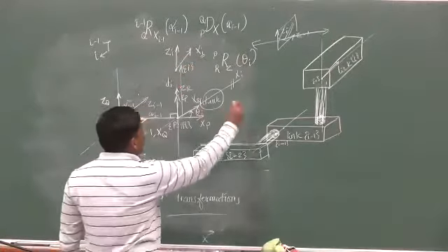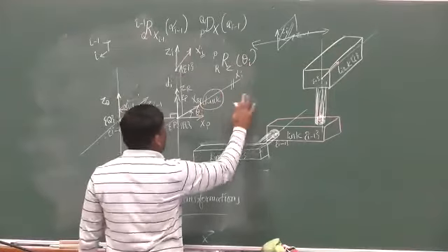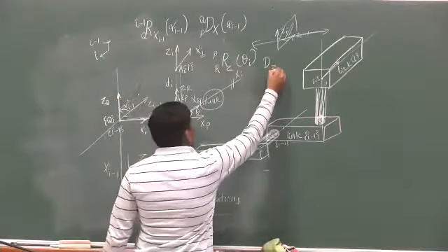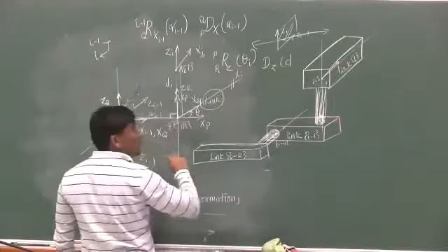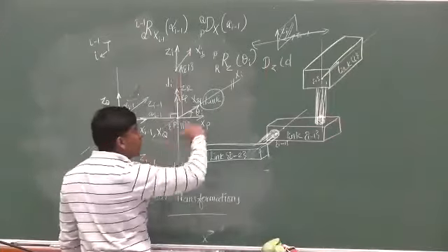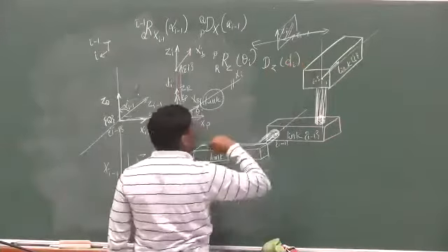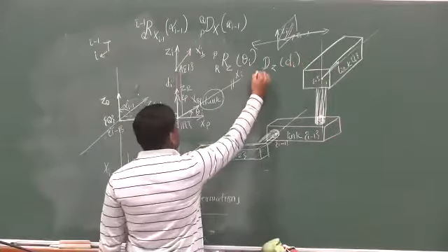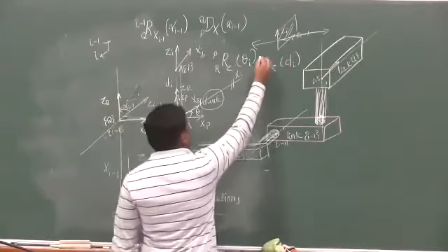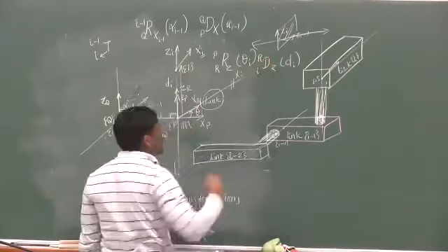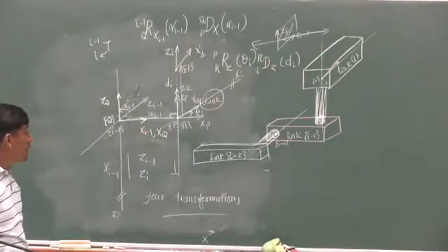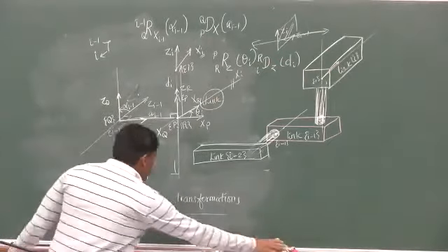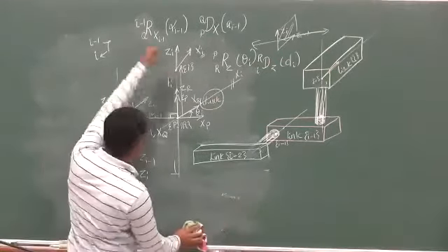So now I am translating along the z-axis by the distance d, and we are doing it along zi, so I am putting di. And what frame are we seeing? We are seeing the frame I, with respect to R. So these are the four operations we have done. Now, in order to give a little more clarity, I am rewriting here.